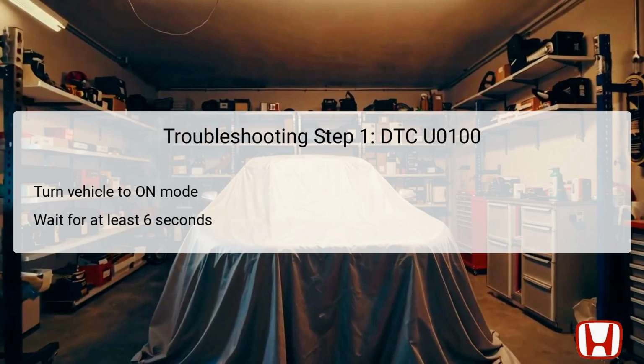By waiting, technicians can observe possible system messages or error codes that may emerge regarding module communication. This initial check helps ensure that the BCM has the opportunity to establish contact with the ECM PCM under normal conditions and is a fundamental part of the diagnostic process.